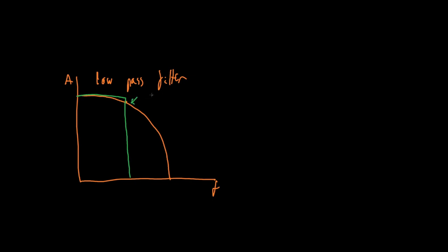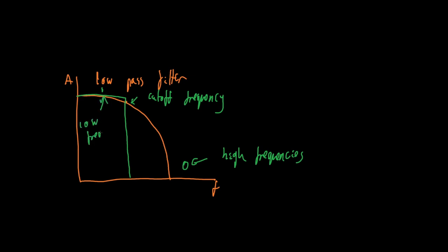After the cutoff frequency, you get to 0. So here's 1 at low frequencies, 0 at high frequencies. Now the low pass FIR filter is based on the impulse response of this ideal filter response. So let's look at that.